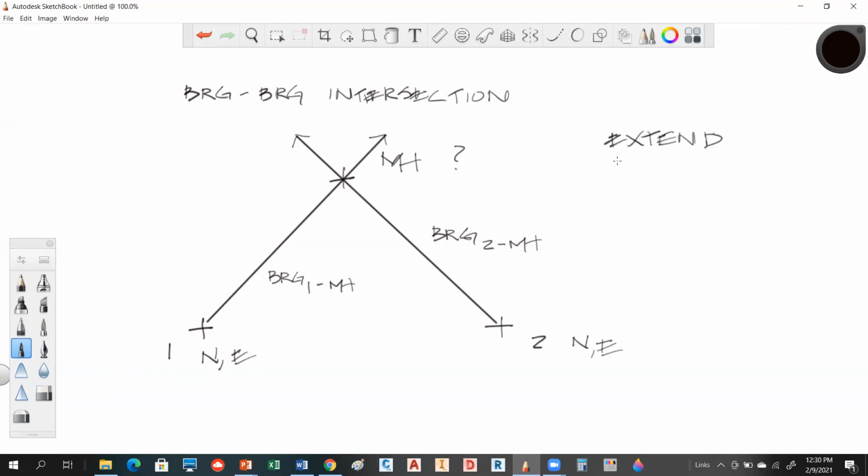That's doing that. So is the trim. Okay. And the other one that works very well is fillet. These guys are all pretty much doing this process right here, as long as fillet has a radius equal to 0. If you set your fillet to a value other than 0, it's going to put an arc in here. Okay, so that's not what we're after. We're not going to have time to do these kinds of things, but this is a process that you use a lot when you're doing solutions for things. Maybe more in the office than out in the field, but you could do this. So this is called a bearing-bearing intersection.